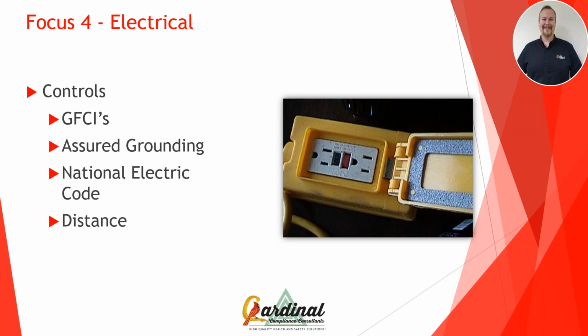A competent person has to go inspect the equipment, inspect our tools, and make sure that they're properly grounded, that we're not setting ourselves up, whether through damage or missing ground prongs, for a shock.